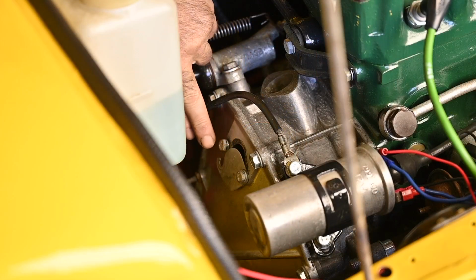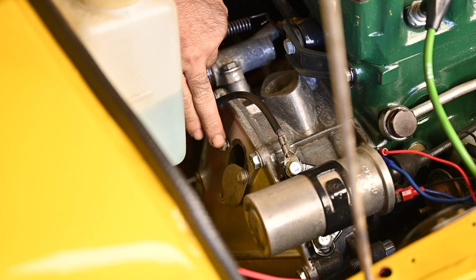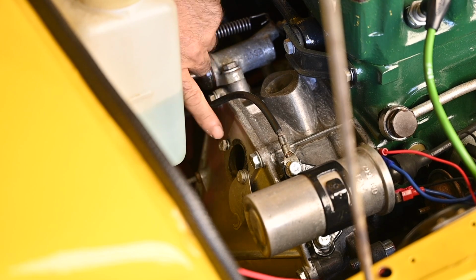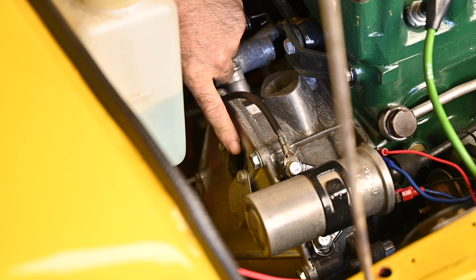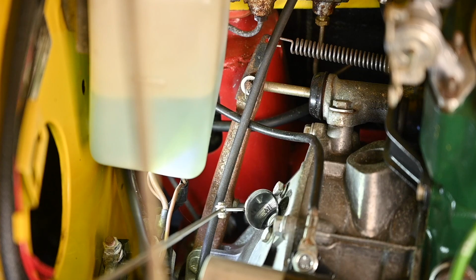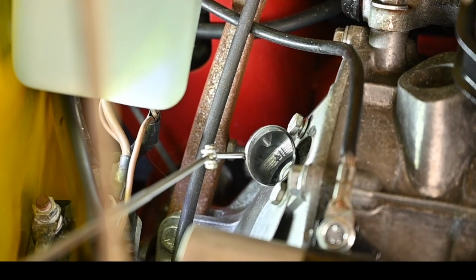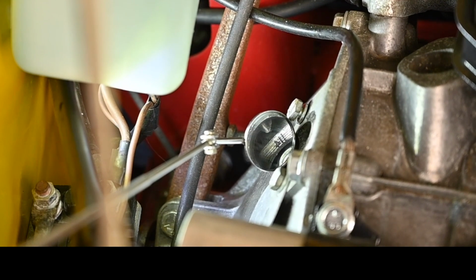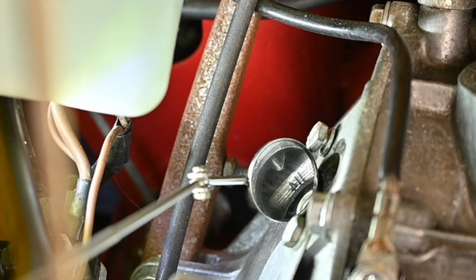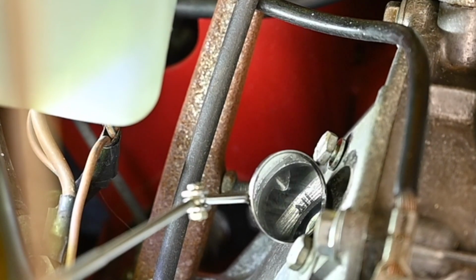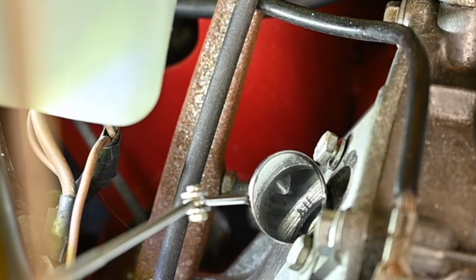For the people that have a Mini amongst you, this is the inspection hole. Unbolt this a little bit, and then you can flip it open. Now you need to look inside, but for that you need a mirror. I hope you can see it a bit. I have my mirror placed right there at the opening, and you can see the marking on the flywheel. Actually, it says 1.4, and on the top of it you have a little notch, and that's how I've set it. That's your real true top dead center.